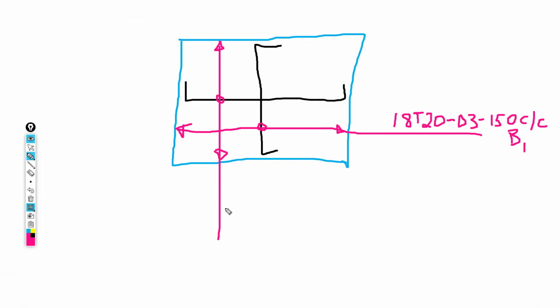I'll put a point of emphasis that I'm talking about that bar. They might be like maybe 15 T20s. So it's going to be bar mark 0.4 at a spacing of, let's say, 175.